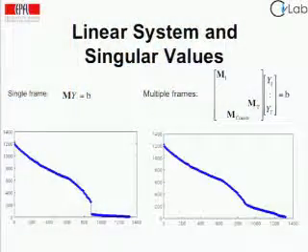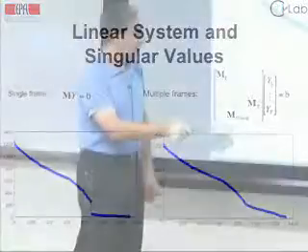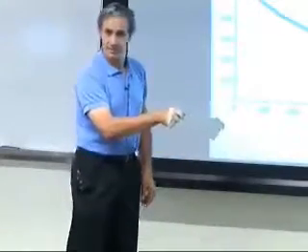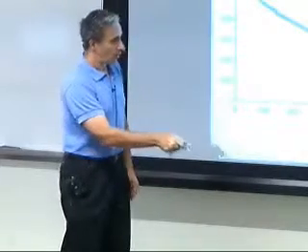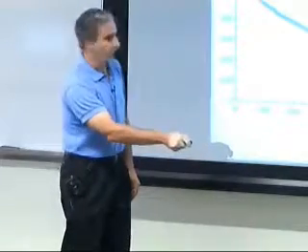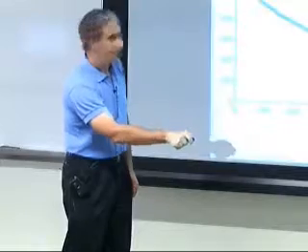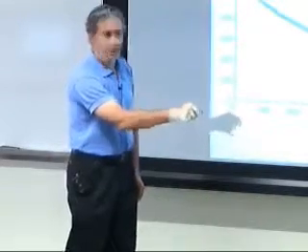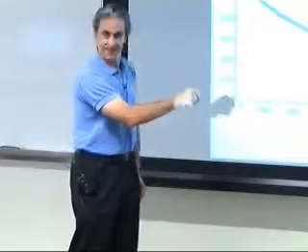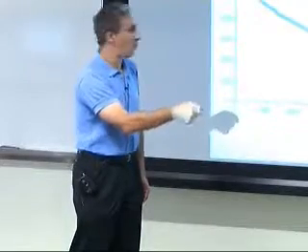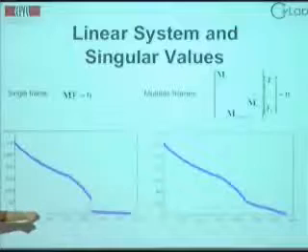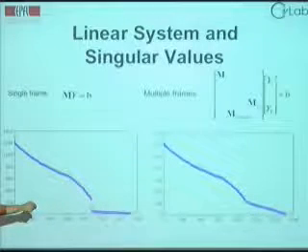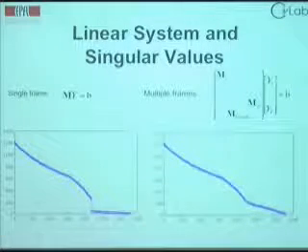And what's interesting about this is now if you look at the eigenvalues of this big matrix, here's the kind of graph you get. All the eigenvalues are non-zero. It's full rank except one, the last one. And the eigenvalues for the first few, the first 2/3, have roughly the same shape. Which is one way to say that at least these modes you haven't perturbed by adding your constraints. You haven't assumed anything about how it deforms, in other words, or very little.